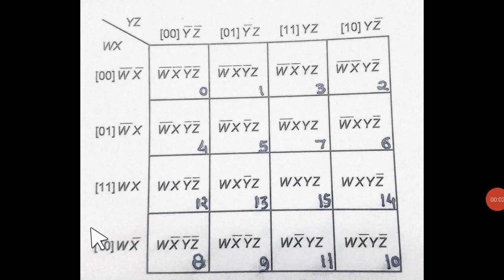So students, you can see a K-map in front of you. It is of 4 variables, WX for the row side and YZ for the column side. There are 4 rows and 4 columns in this K-map, and you can check the values 0 0, 0 1, 1 1 and 1 0 because it's following the gray code. So 0 0 will produce W dash X dash because we complement zeros. Similarly on the column side, 0 0 will produce Y dash Z dash.